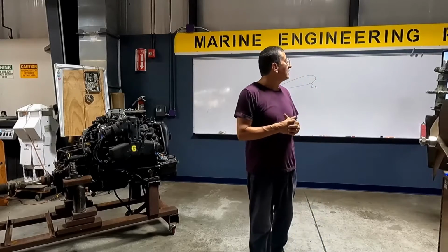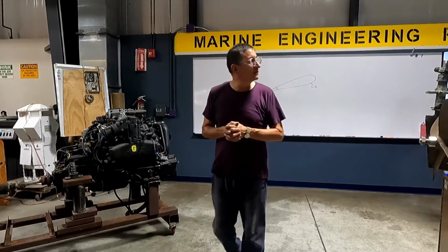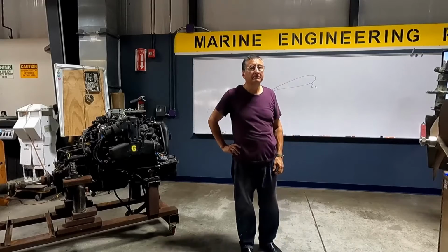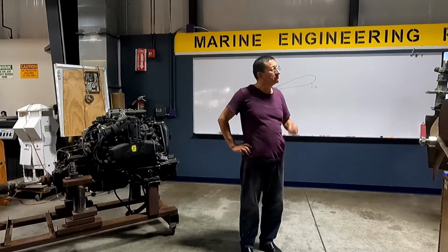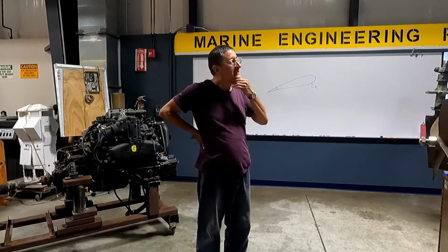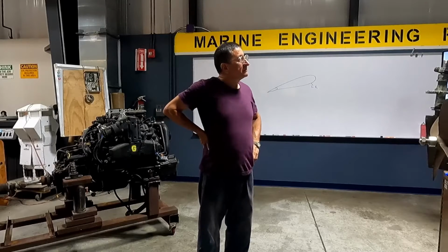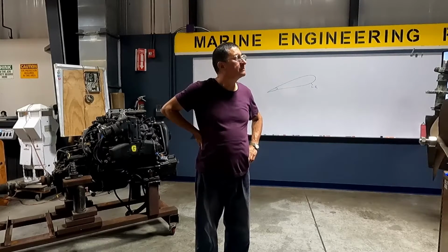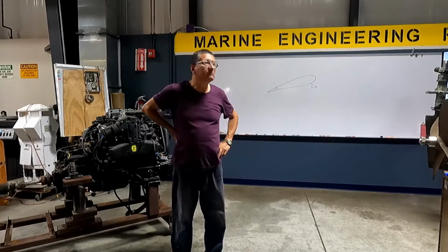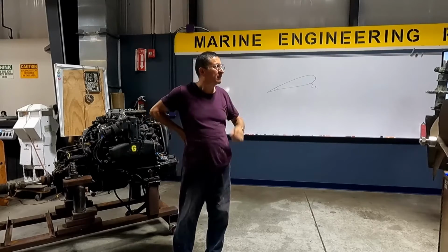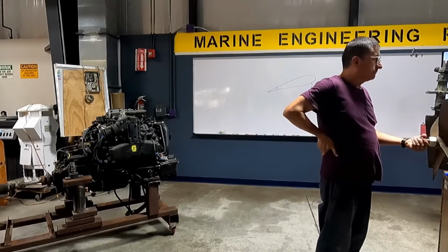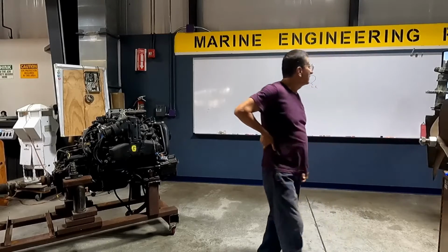Propeller with high pitch. I just want to say, just think about when you have your tires from your car and you put a bigger tire. Yeah. Your miles is different now. It's the same thing. The tire, the propeller is like a tire for a car. You know, so if you put bigger tires, like my buddy did, now he says he's doing 55 and he's doing 65. So because you got bigger tires, every revolution gets more distance. The same thing is, you get more volume with a bigger diameter prop than you do with a smaller. Yeah. Just so everybody knows. That's just the example. Danny, can you answer? Yeah. Look at the next one.